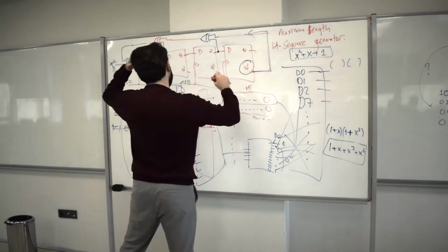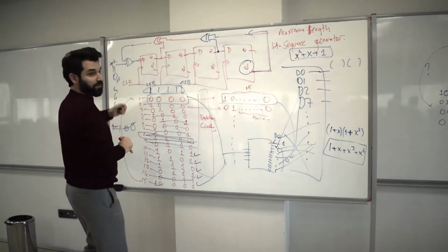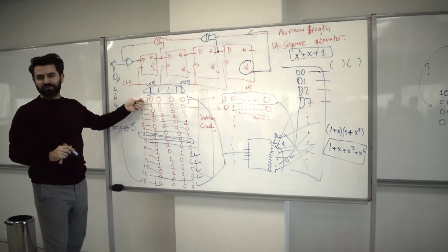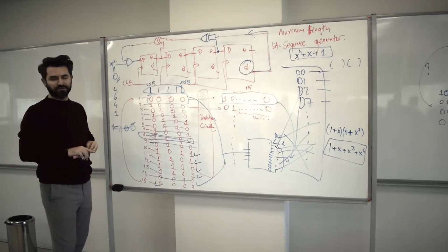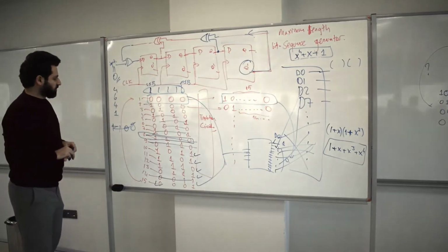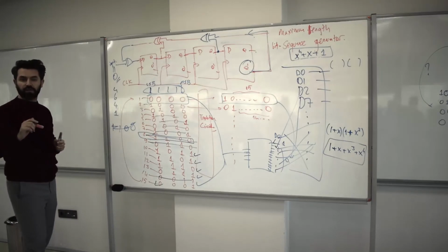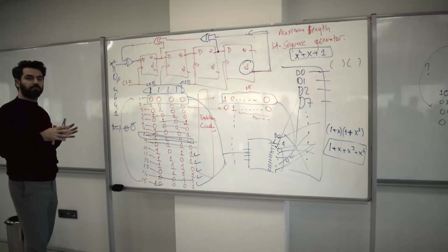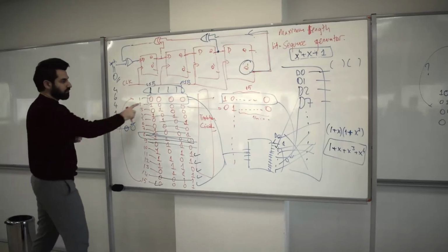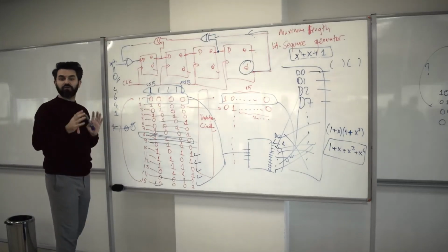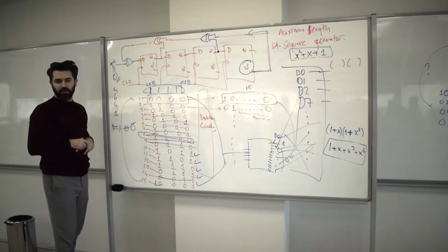But in that case, if you start from 0-0-0, you have to initialize it. Otherwise, it will not count. Okay? So let me give a talk on this, because I'm not sure about the following. Would it be a maximum length bit sequence generator if we need 15 or 16 possibilities? Sometimes people don't count all zeros as one of those counting patterns.